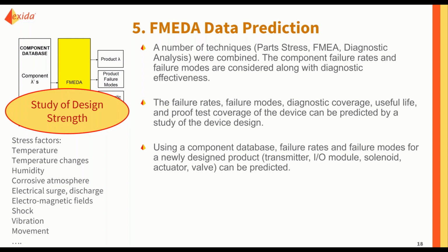Well, you have to create a component database, which you see in the upper left-hand portion of your screen. And the FMEDA technique, if it has a good database, can predict failure rates and failure modes, diagnostic coverage, and useful life in a very realistic way. And I'll explain that in just a bit.